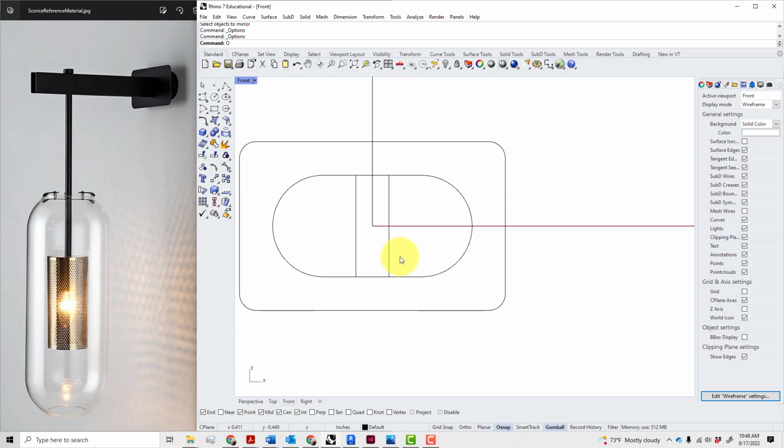Okay, so we're going to now do some more offsetting. I'm going to assume that this steel is 16 gauge, so we're going to go 16th inch. 16 gauge just happens to be 16th inch. Don't think that, like, 12 gauge is 12th of an inch. That's not how it works. Alright, so we're setting that up. Alright, so we have the main structure. I think we have enough now.